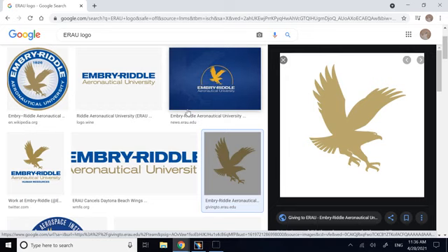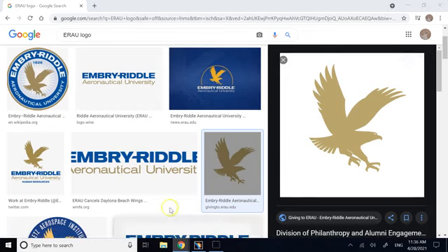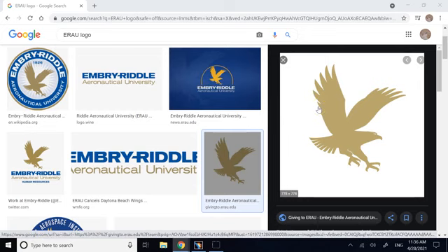This environment is going to be really useful because many objects are thin, or their 2D profile stays relatively constant or at specific draft angles along the third dimension. So for many of these objects, doing the repair is as simple as drawing the outline of the part in a CAD environment, creating an extrude with some thickness, and then printing it, right? So the Sketch Tracer environment can be really good.